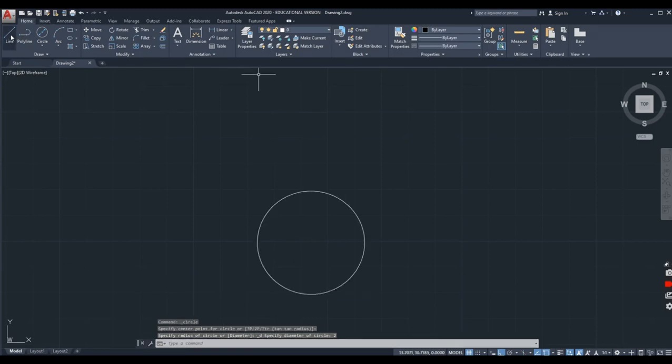Okay, I'm going to draw a line from that center, and I'm going to go straight up, and that's 2.25. Okay, I'm going to go between those twos. That is where those two holes are going to be. Okay, on each side it is 1.5. It's 3 total, so I'm going to put 1.5. I'm going to hit enter again, go from here, 1.5, hit enter.